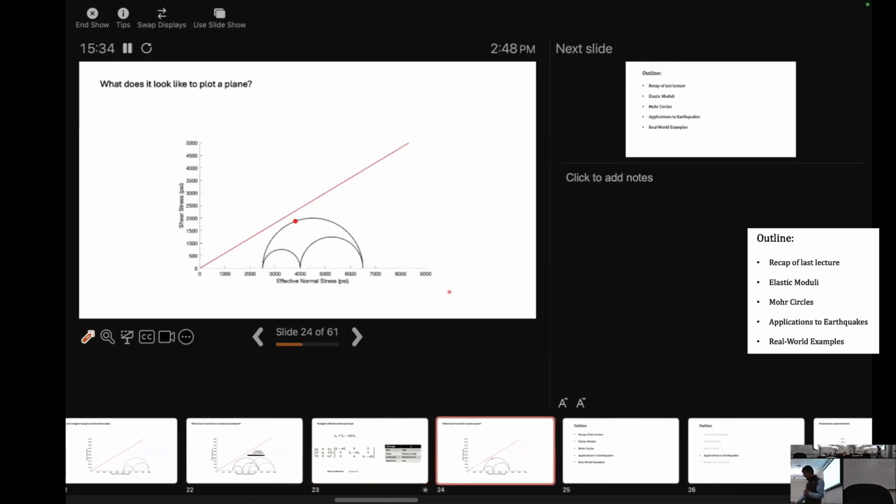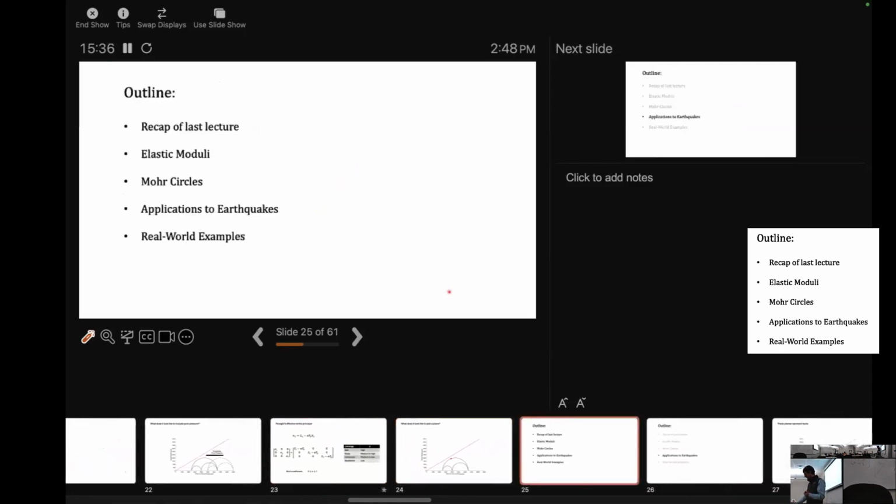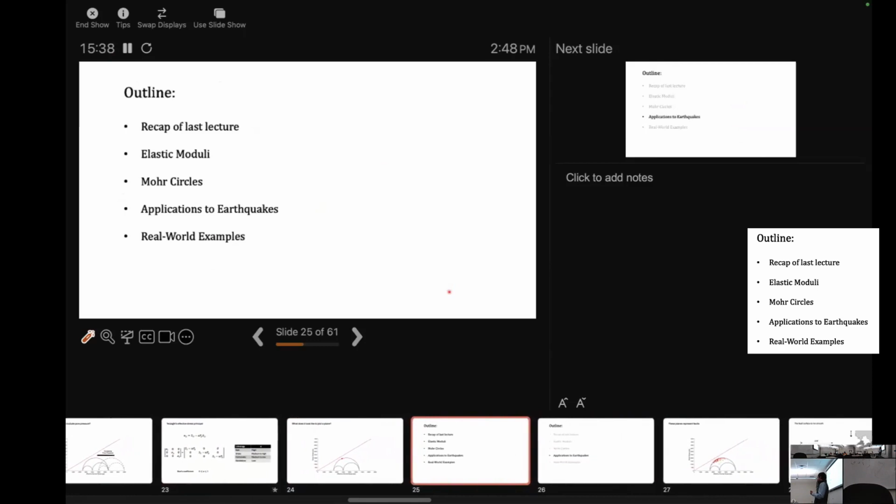We already covered this. Can I ask something? For the Biot coefficient, theoretically, I believe it's between 0 and 1. But in a lot of lab tests, it's larger than 1. Oh, interesting. Yeah, I've seen a lot of literature saying that the Biot coefficient can actually be larger than 1, like 1.2, 1.3. Oh, interesting, I didn't know that. In lab tests, the reality is a little bit different, but if you look at the derivation of alpha, it's supposed to be between 1 and 2.